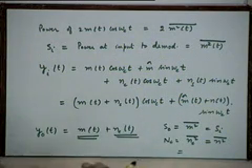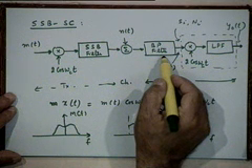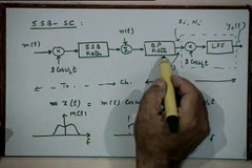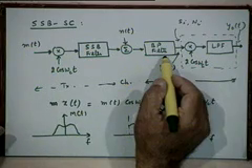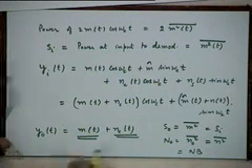What is the bandwidth of this band pass noise? It is not 2B, it is simply B, because this band pass filter has to have bandwidth only of B hertz, not 2B hertz. In the case of AM it was 2B. So, it is N by 2 into B plus N by 2 into B for the negative frequency part. Is that clear to all of you? So, the total output noise power once again is equal to NB. So, nothing has changed.